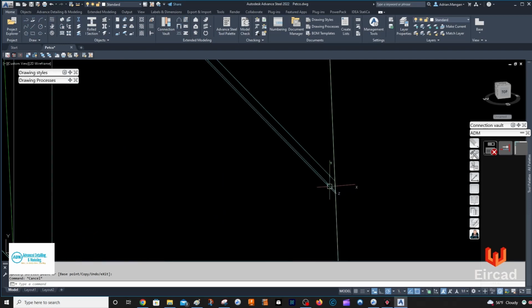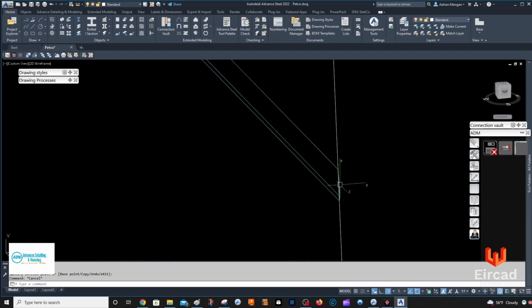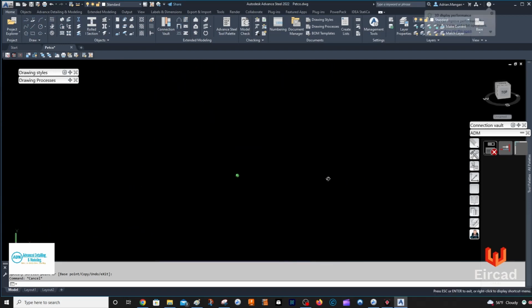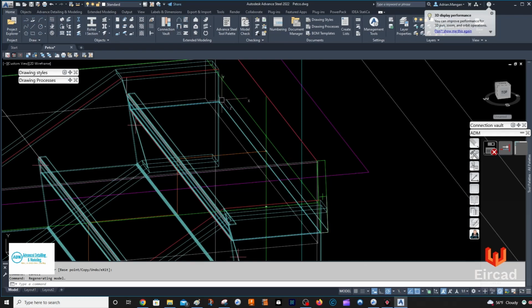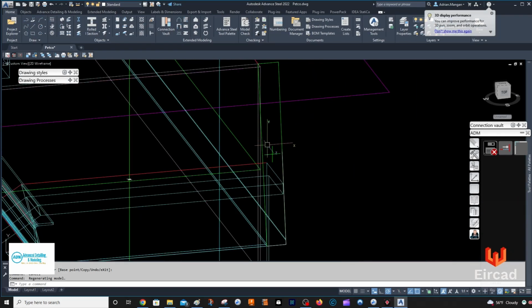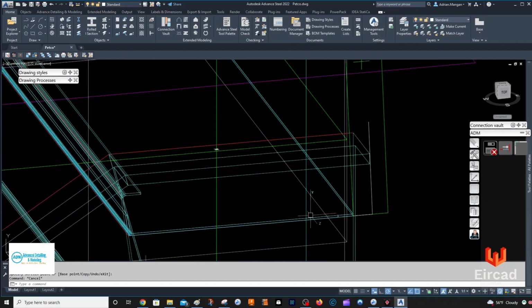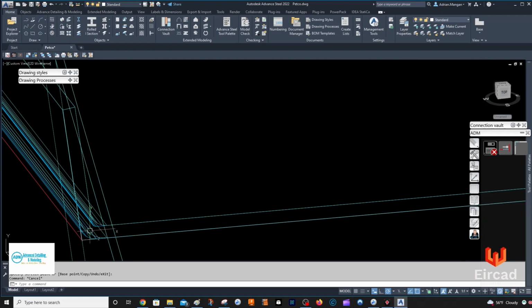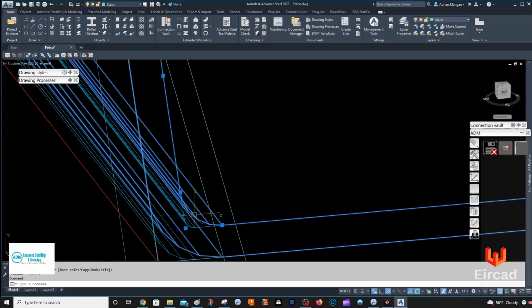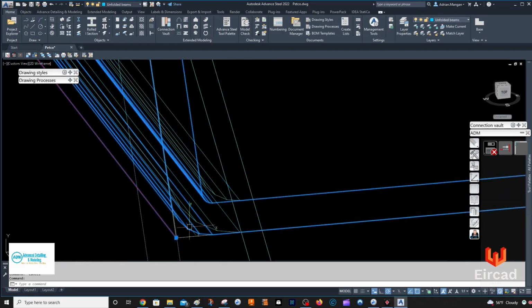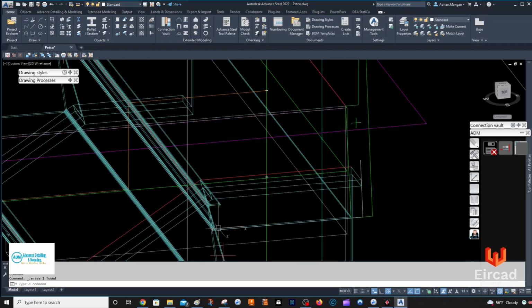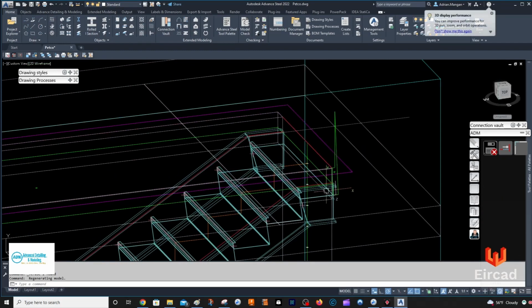You can see we still have a piece here, so it's not perfect. So obviously if you output this now, it's going to have this piece here on the corner, which you don't want, so you can just drag that away out there. And now you have your 2 pans. There's actually 2 there. You can see the radius is slightly different. So I'll delete the one I created manually there, and here's the one that I just cut off the other one.